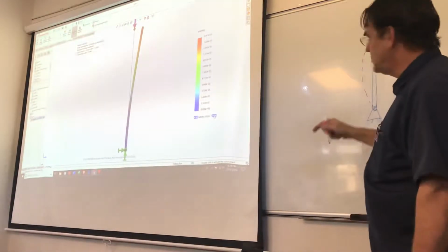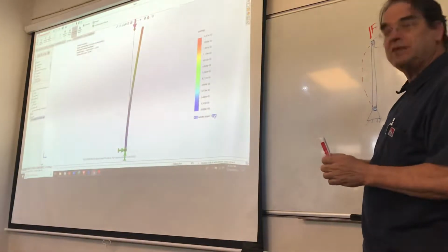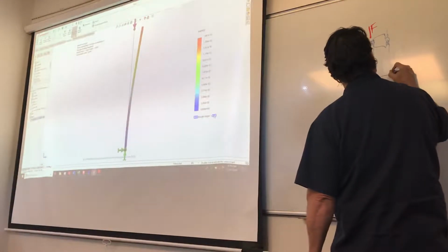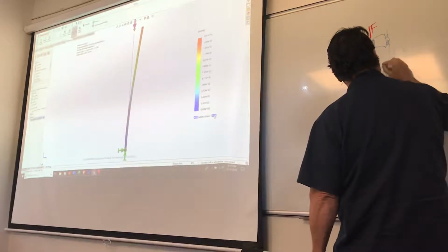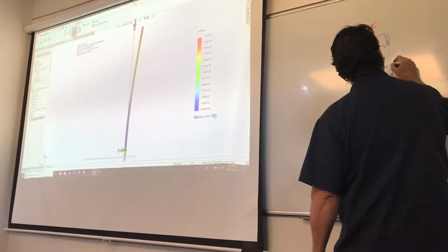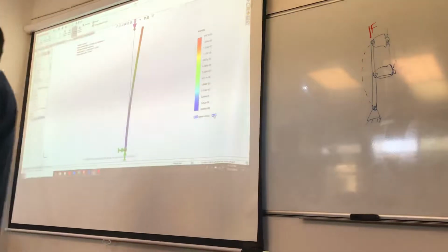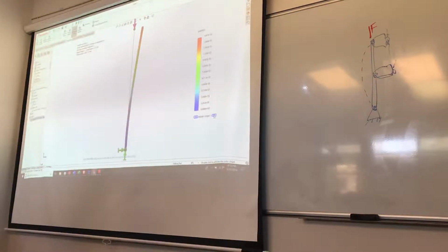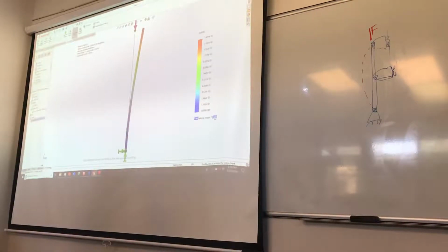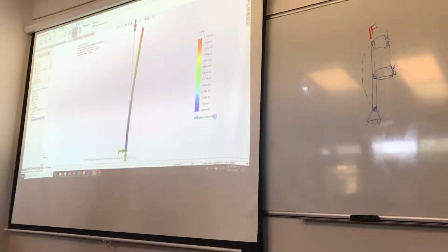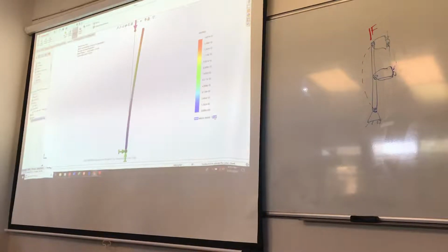Now, one of the ways to eliminate this mode is to say, let's brace it. Let's put something else in here. Okay, that eliminates that mode, because what we've done is we've prevented that mode from happening in there. We've braced that mode out. This happens all the time in the building industry. When they're building structures up, they have columns. The columns, of course, want to buckle. What do you do? You put floors in. You've got floors, all kinds of other ways that are stopping the column from having that buckling mode.